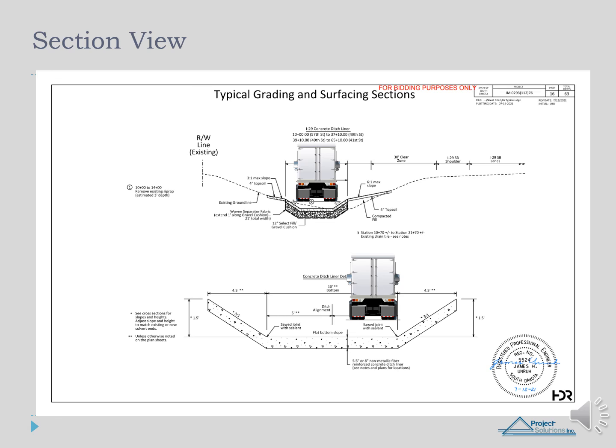Finally, we have the section views. This view is a cross-cut and would be like looking at the rear end of the truck. Here we can see the slopes of the road and of the land at different stations. It is not uncommon to have multiple section views at each different station so we can get a sense of the overall plan.